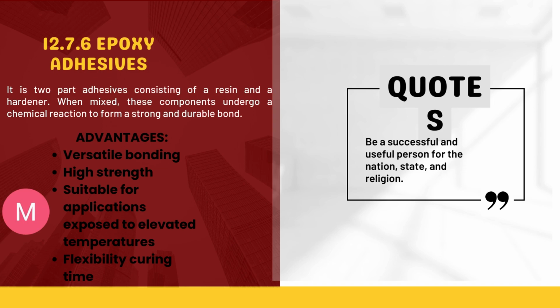Next, the epoxy adhesive is a two-part adhesive consisting of a resin and a hardener. When mixed, these components undergo a chemical reaction to form a strong and durable bond. Advantages are versatile bonding, high strength, stable for applications exposed to elevated temperatures, and flexible curing time. It depends on what kind of composite.